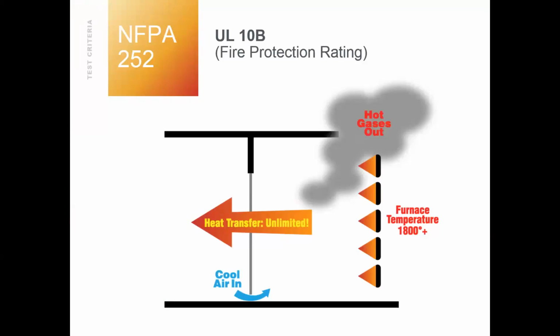Essentially, those are all good answers. It's more to test the structural integrity of these products that were in there. Under UL10D, it's a non-structural test. Under UL10B, it is a structural test. And then once you put a rolling steel door within this opening, it gets burned under an 1800-degree furnace for 3